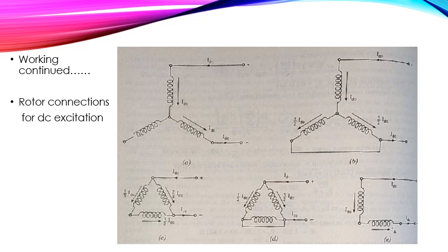So from this we understood that unbalanced secondary heating is unavoidable with a three-phase secondary, but with a two-phase arrangement the heating can be equalized, right? And that is shown in figure E. Now the rest of the connections show three windings connected in series or in parallel, right? And the heating is unavoidable. But using only two windings, the heating can be equalized, right? But the induced secondary EMF at standstill is high, and that causes the insulation problem.